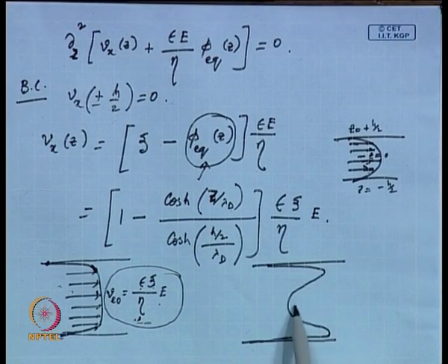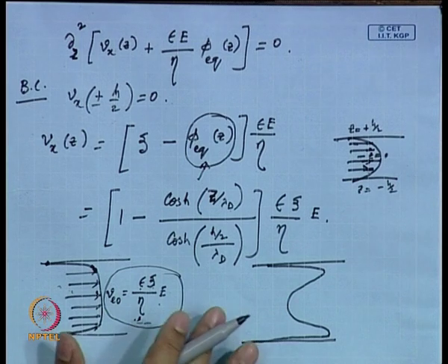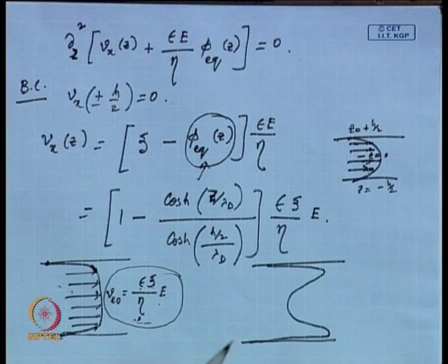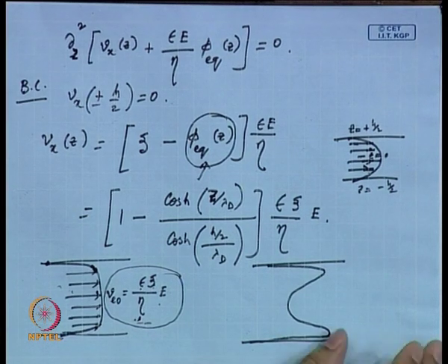So, this would be the velocity profile that we are looking at, and with this velocity profile, now you need to know against how much delta p this electroosmotic pump can still work. You have a pump in place and you are pumping through a media, and that media would give a back pressure of so many Pascal, so many atmosphere. So, you need to know whether the pump can deliver that kind of pressure or not, otherwise this pump will not work. So, we need to solve this velocity profile, and find out the limiting value, when this velocity is 0, that is the limit.